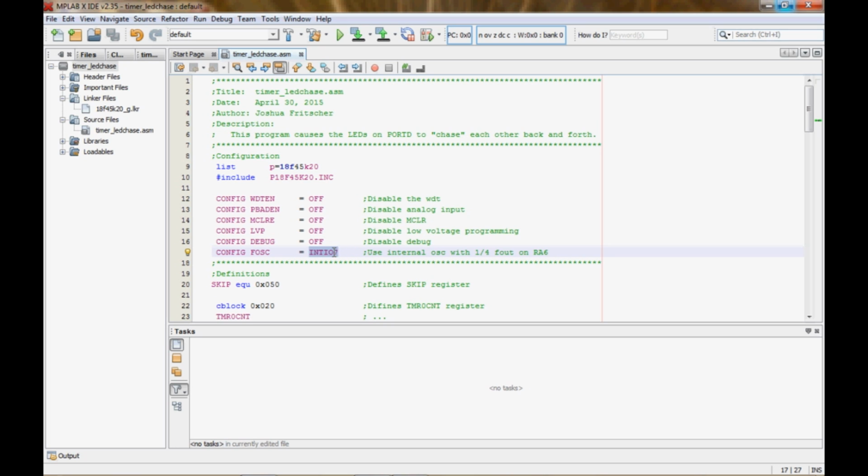And for you new fellas, the input output pin RA7 is used if you're going to use an RC oscillator. You would usually set that up on pin 7 with a resistor to power and a capacitor to ground, and both of them going to pin RA7.